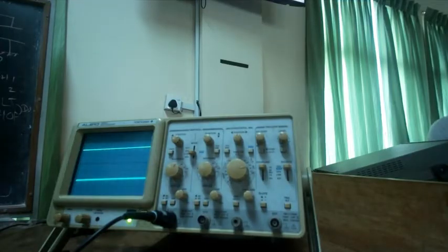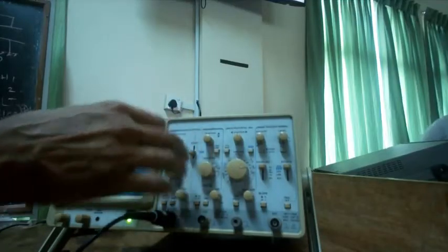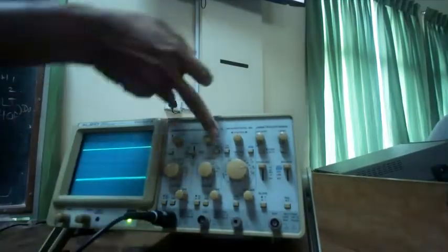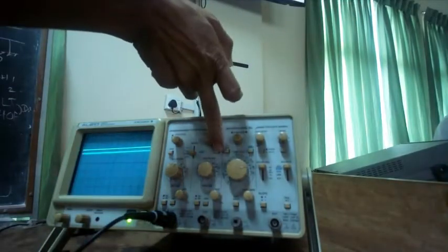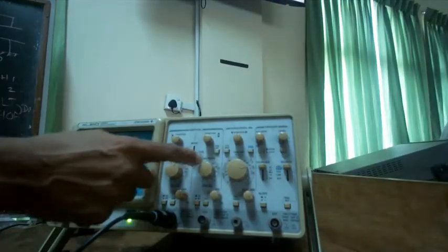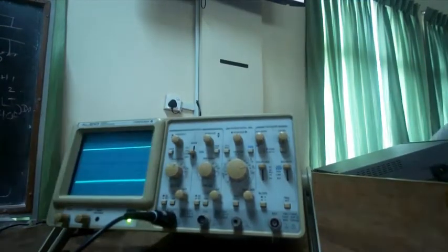Also, sometimes there is another one in channel 2, right? So here is the invert button. What it does is it sends channel 2 through an additional inverting amplifier. So it's as if you are multiplying it by -1, right? Inverting amplifier. We will learn about inverting amplifiers later. It's a very simple circuit.